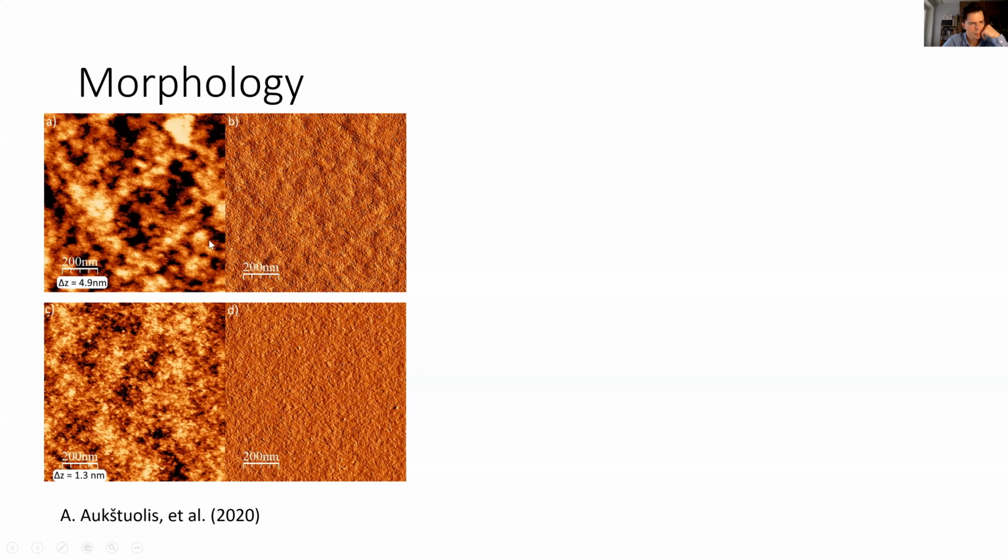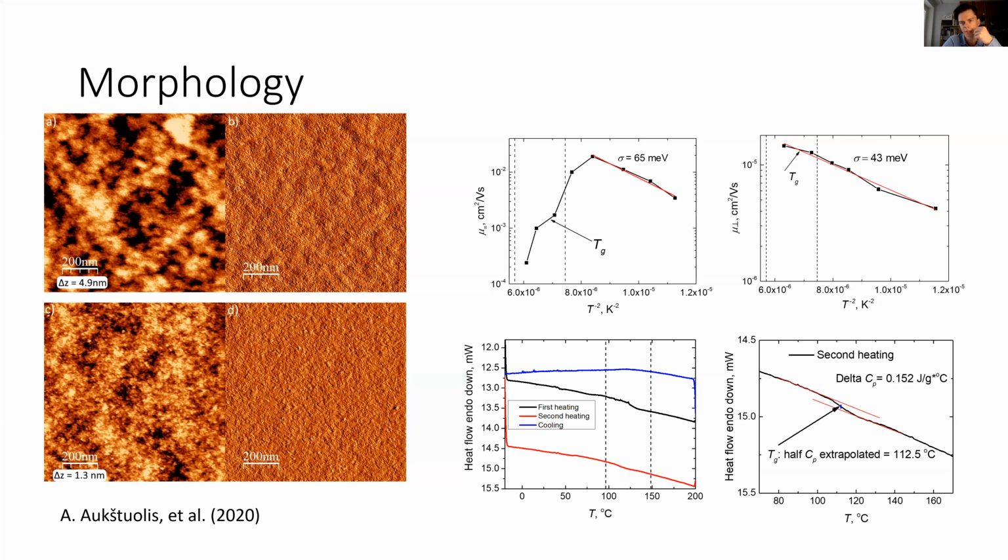they move in a thin area near the dielectric layer, and every small change in the morphology is crucial for those holes to transport. In this case, where they move perpendicular to the substrate direction, they move in the bulk material, and the disorder is different and the morphology is different in this direction. So the thermal activation is bigger. So we see an increase in the mobility over the whole heating range, over all the temperatures, where we see no decrease.